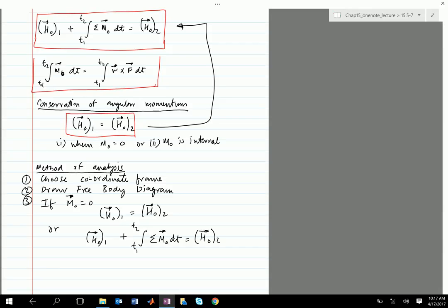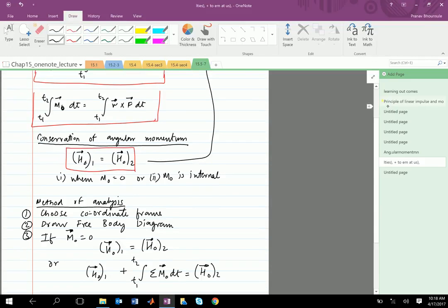Okay. So in general, first identify if it's a particle problem. Once you know it's a particle problem, think about whether things are moving at an angle to the application of force. If they're moving in a linear direction, then you don't have to use angular momentum or angular impulse. You can deal with the problem with linear impulse and momentum. When things are going in circles or in a direction to the force, that's when you typically have to apply angular impulse and angular momentum. Okay, so let's do the problems.